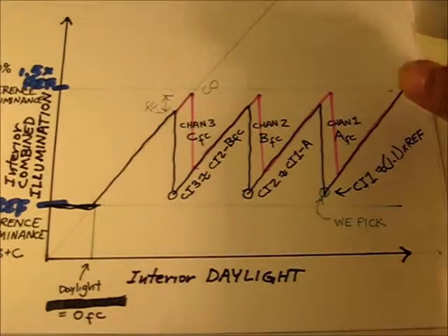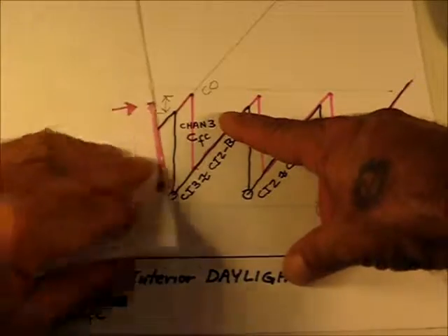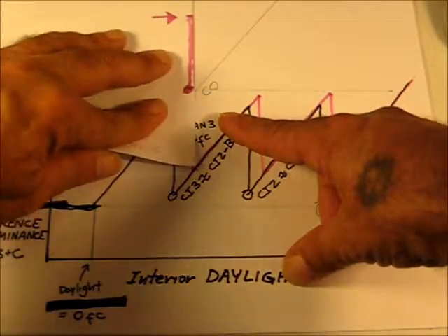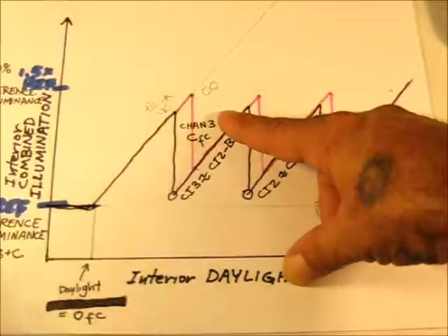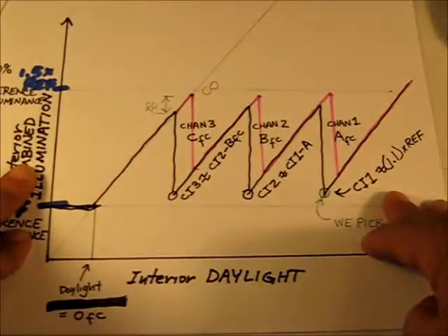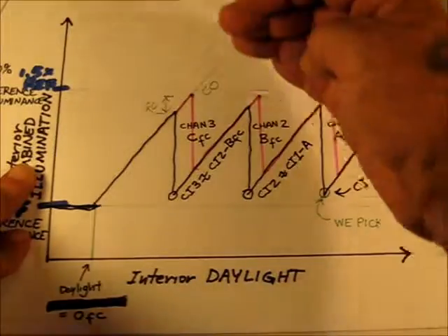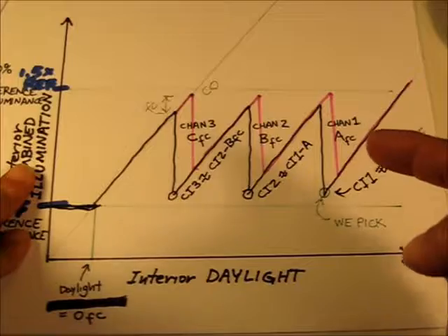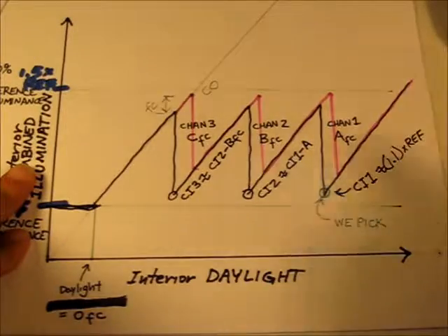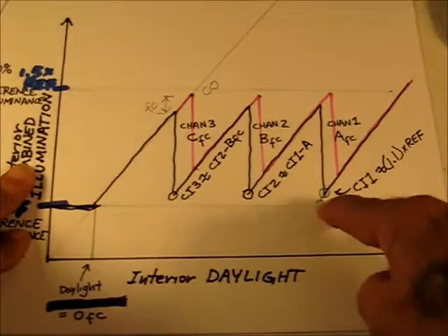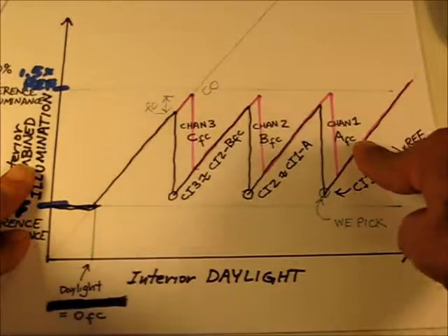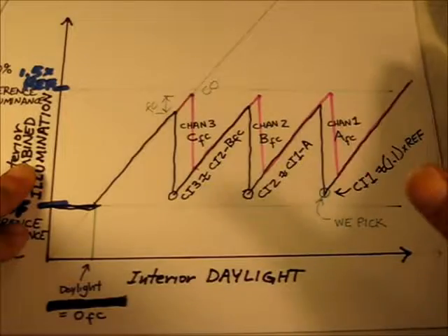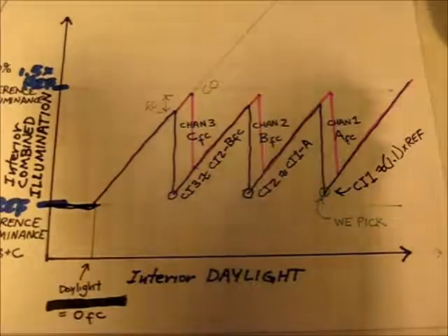That's your minimum deadband, and a formula that you can use to determine when you're going to exceed this point, which is your maximum deadband. And if you put it anywhere in between there, you will be Title 24 Part 6 compliant in the state of California. And all you got to do is pick one point, take good measurements, and plug in the numbers, and you're done. Fantastic.